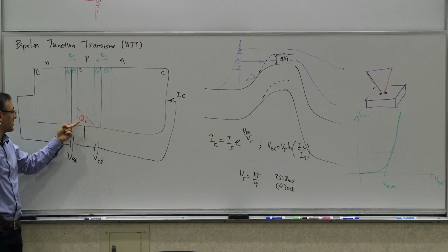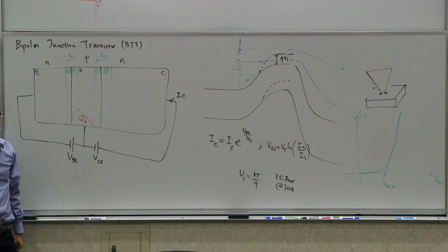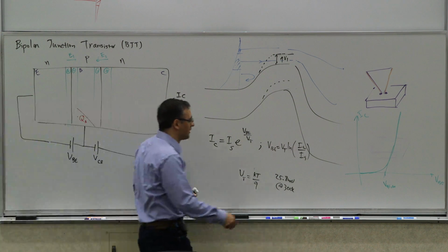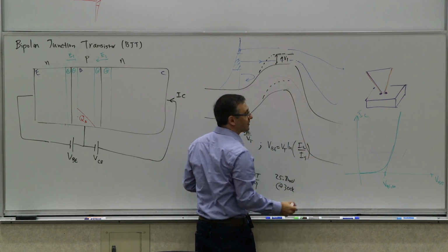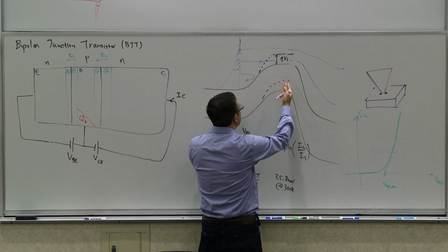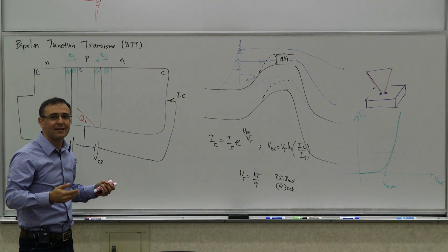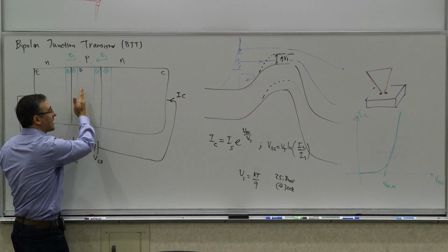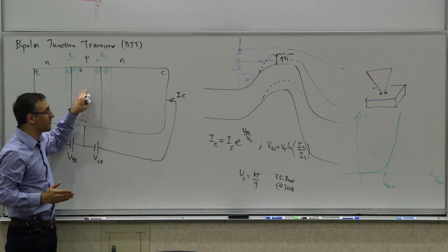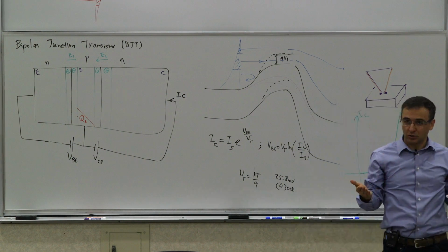Okay, so that's a good point. So she said the depletion regions combine. What happens if depletion regions start hitting each other, start getting into each other? What happens to your energy band diagram? Well, it starts becoming flatter and flatter, right? Then you don't have this behavior, you lose your control, and you have reduced and eventually removed the isolation, the separation of the output port from the input port, the controlled from the controlling, right? So you can't afford doing that, right?